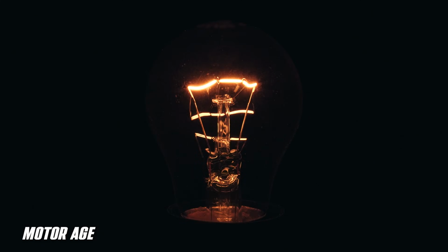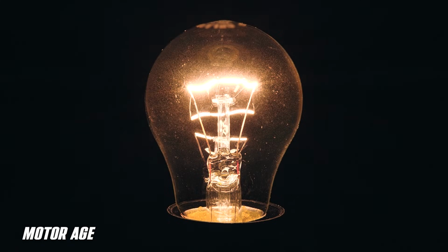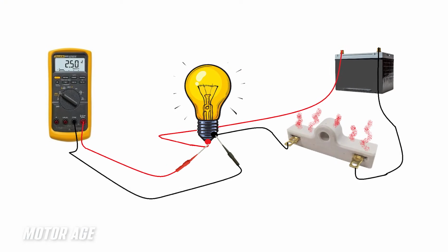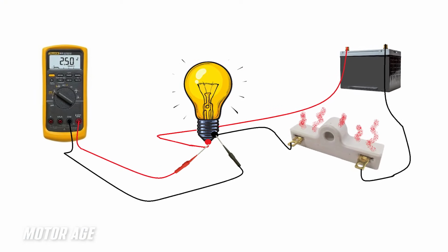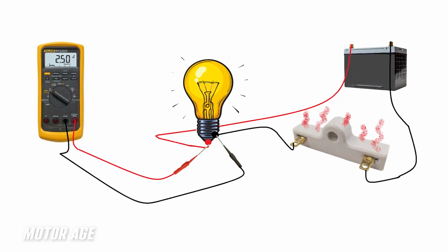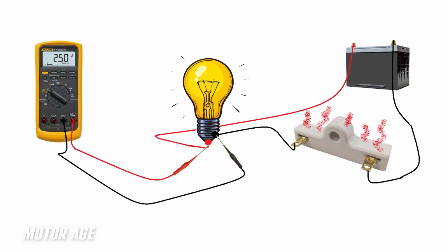And there is another point I want to bring about. Current flow is the work truly being performed in a circuit. So, for instance, if we were monitoring an electric stove or a rear defroster grid, as those circuits begin to function and current flows through those circuits, the resistance within those circuits creates voltage drop, pressure drop, electrical pressure drop. And the results of that pressure drop amounts to heat. And heat given off in the form of light or actual heat that we can feel that melts ice in the case of a rear defroster grid or boils water on a stove. That heat is the result of that voltage drop.